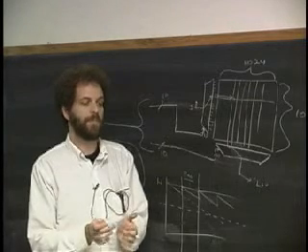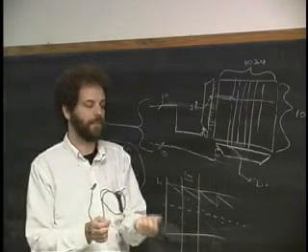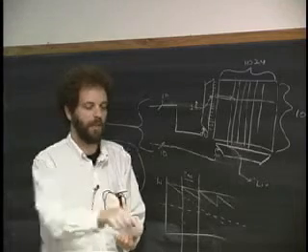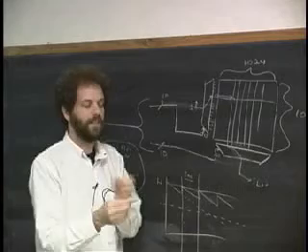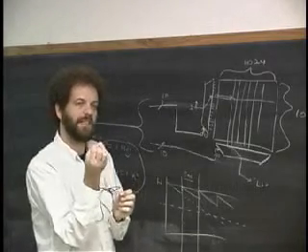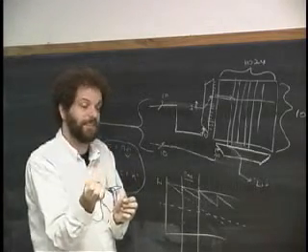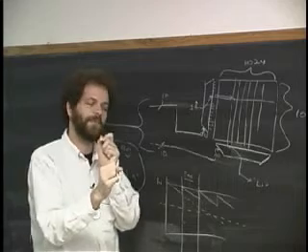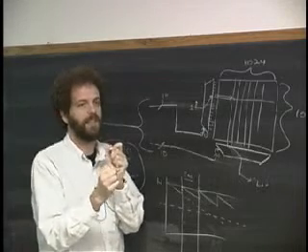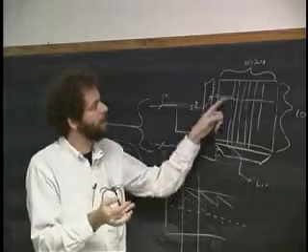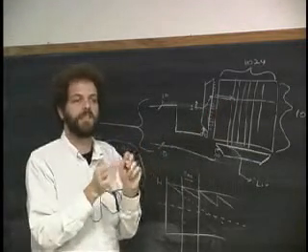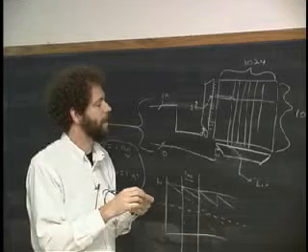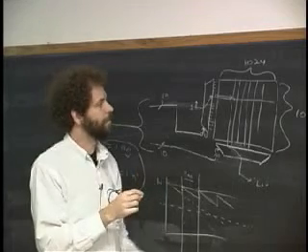But what happens when the tubs get really, really tiny, a little thimble for each one? Then when you say, okay, you there, let me suck on my straw. Did I get water or didn't I get water? Well, you know, if the thimble is this big and it gets tiny and tiny and tiny until it's just a drop, did you get a drop or didn't you get a drop? It becomes tough to tell. So there's a trade-off of how large the cell is here and how difficult it is to sense whether it was a full or an empty tub.